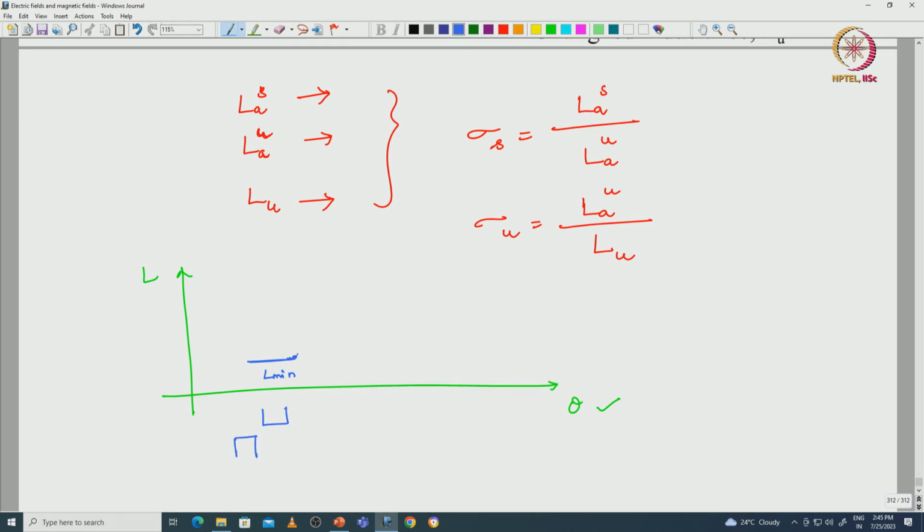After this point, with the excitation, the rotor pole will try to align with the stator pole. The moment the alignment or overlapping starts, the inductance will rise linearly, and once it is completely aligned the inductance will be constant.